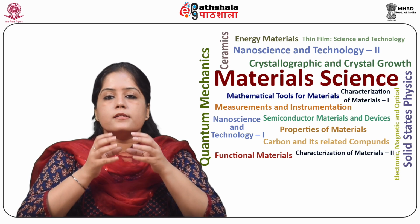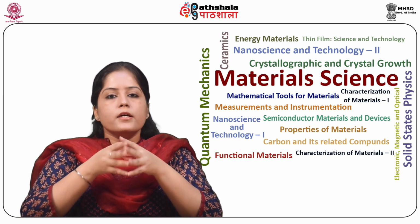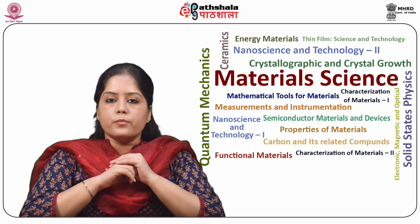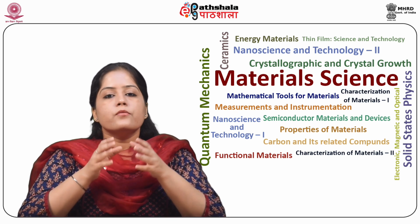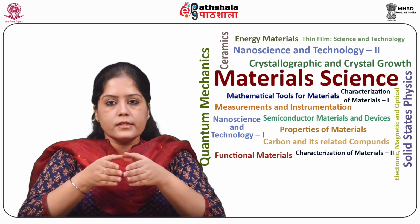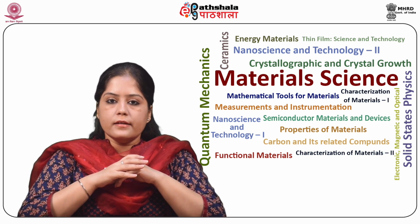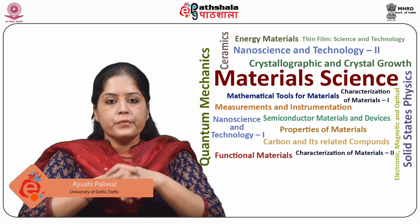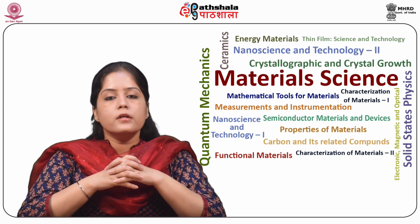Next, the information, that is the signal charge carriers Q info, is injected into the semiconductor near the oxide interface just after the application of gate voltage, where they will get accumulated in a potential well. Now we also discussed the three-phase CCD, which consists of a linear array of MOS capacitors where the electrodes are connected in groups of three-phase periodic waveforms. Lastly, the charge carriers at the input can be generated through avalanche injection or optical injection, and the output arrangement of a CCD consisting of a reverse biased PN junction diode was discussed.